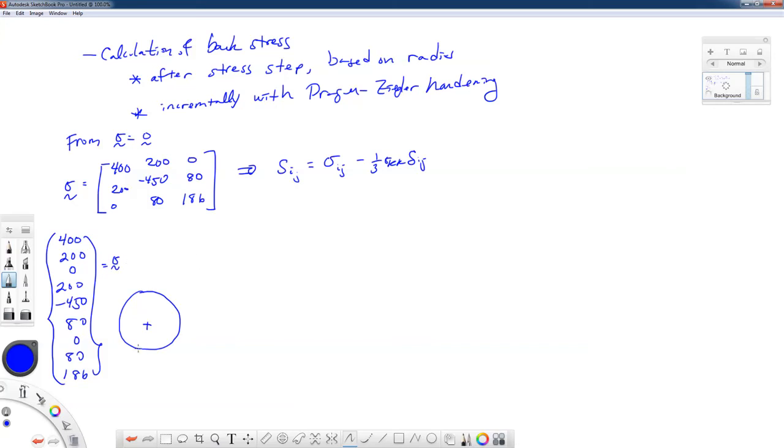Now we can do this in either regular stress space or deviatoric stress space. There are certain advantages of working with deviatoric stress space, and that's the fact that we do get the hypersphere for the J2 criterion. And just to write down J2 again, it's 1/2 Sij Sij, again with the summation notation.